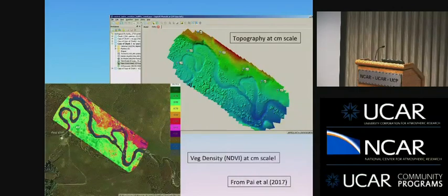In the past, it's pretty hard to estimate how much of this shortcutting might actually occur because it's hard to measure the hydraulic gradient, the difference in hydraulic head between these two places. You have to have somebody stand out there with a stick and a staff rod. You need to know the hydraulic properties of the material. That's also difficult. But for us, when we flew this, because we did a digital elevation model, we now have a map of the stream elevation or the water surface elevation all the way up this drainage.